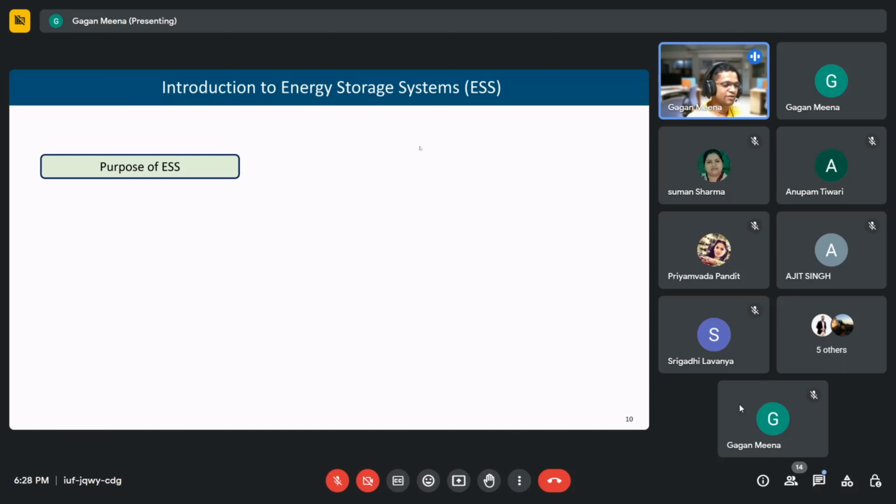They are generally used for long duration discharge, for 6 hours, 8 hours. And lithium ion are being used for 2 hour, 4 hour discharge duration. So right now we are using only 2 hour and 4 hour batteries, and those are all lithium based. Everywhere throughout the globe, these grid scale batteries are lithium ion based, and they have a discharge duration of either 2 hours or 4 hours.